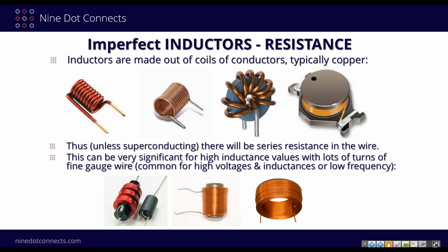Now this can be very significant in the case where you have a high inductance. When you need a high inductance, as shown below, you need a lot of turns to make it, and you do that because either it has to support a high voltage for a long time, or because you have a very low frequency. So it can be a low voltage for a very long time, or a very high voltage for a short time. So high inductances have lots of fine wire. Lots of fine wire is a lot of length of something that's small in diameter, and the resistance goes up.